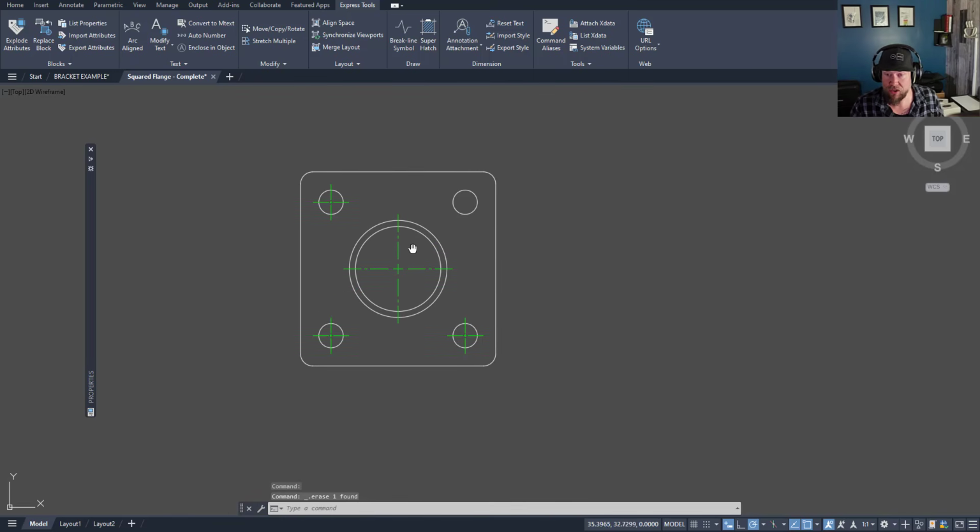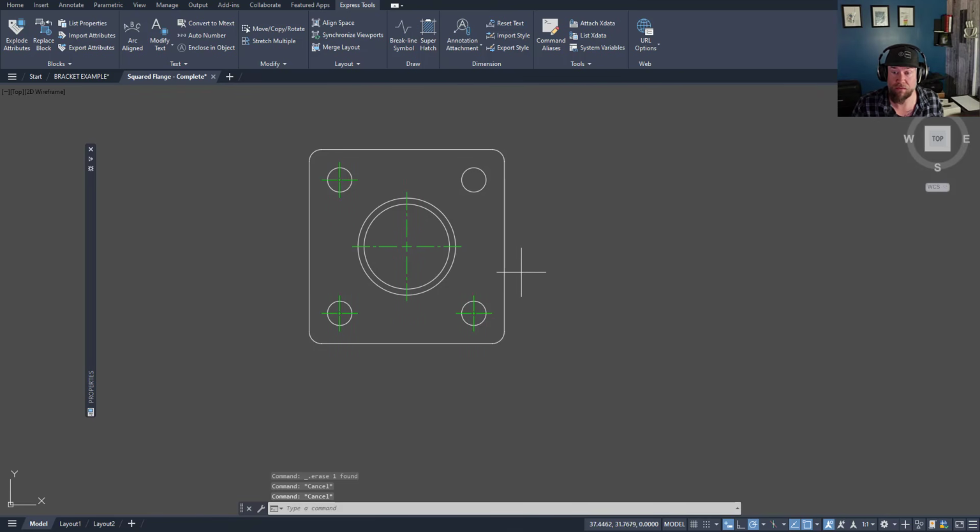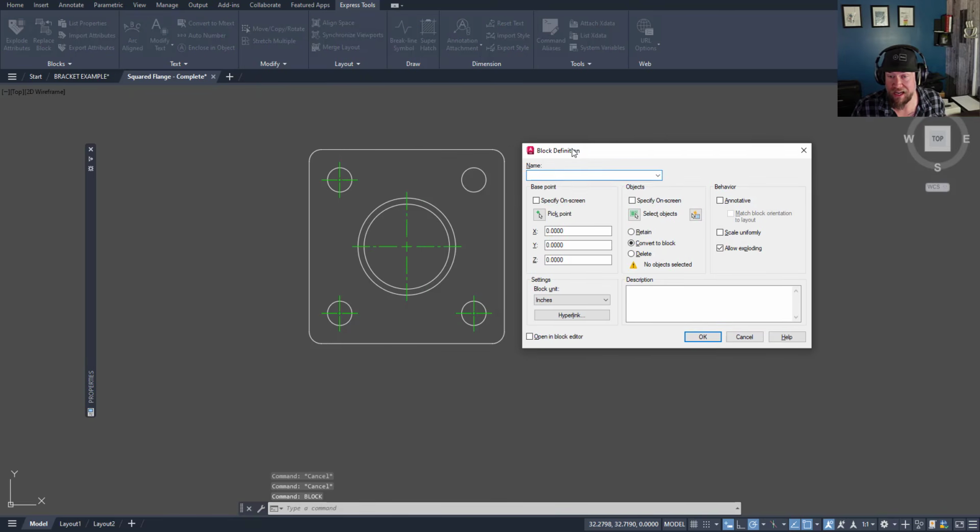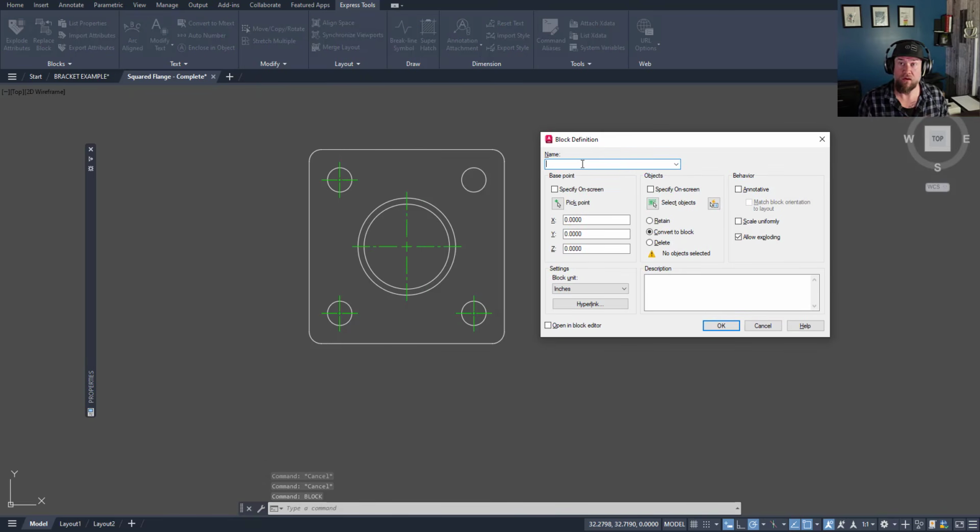So perhaps you're using this a ton of times within your floor plan and your project. This is just a group of individual items and line work within AutoCAD. But by typing in the word block, you can create a quick block without anything special. If you'd like to get into dynamic blocks with customization, options, scaling, all of that, I have videos on that on my channel, and I highly recommend learning that.